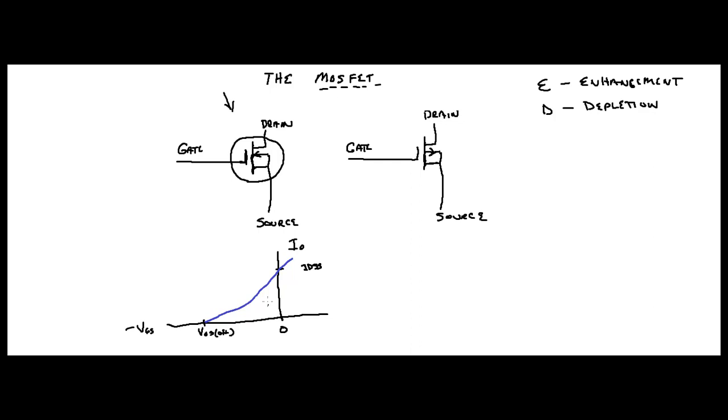So basically what this is saying is if you have a circuit and there's no voltage at the gate, suppose your gate voltage is just say 0. If you make that voltage negative, that means you're going to get less current, right? Because your current's going to come down here.